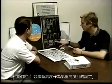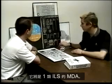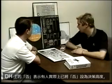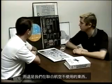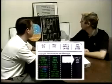We reference the Cat 1 decision height as a barometric altimeter setting, and that's what MDA would be. It'd be an MDA for a Cat 1 ILS. The NO on NO DH indicates that somebody has actually set NO as a decision height, and that's something we don't use at United. Fifth column, AP1 and 2.